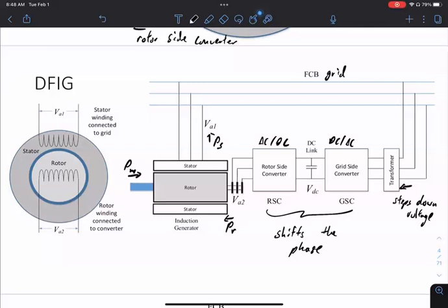Good question. That goes back to why this took many years to develop. This concept is not new. When people were designing wind turbines, this was proposed. What you need to do is change the voltage and phase angle, and this is one way to do it. The reason you had to wait many years is you had to wait for these to be high power enough and reliable enough. And then as you said, for the control to be good enough to track everything. You need these to be reliable enough under high power operation.